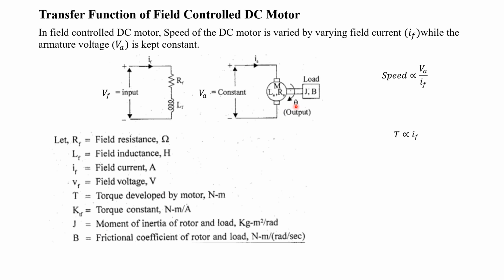There will not be any elasticity coefficient. Here what we are going to find out is the transfer function, the Laplace transform of output, that is theta, divided by the Laplace transform of input, that is VF. So we have to find the value of theta of S divided by VF of S. To find the transfer function, first we have to draw the equivalent circuit for this field.